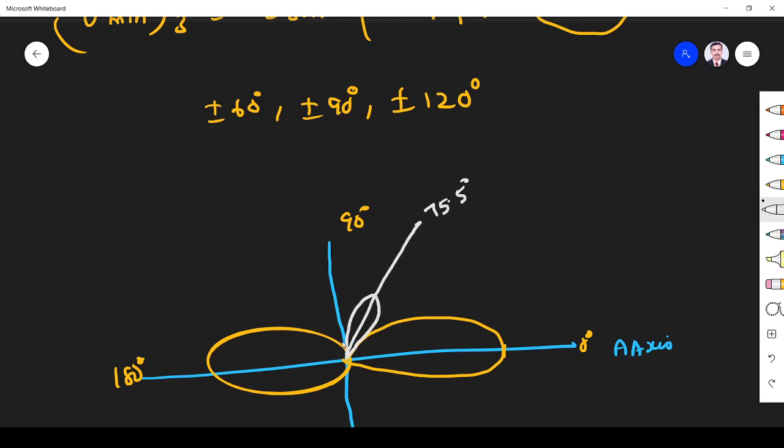And this is 104.5 degrees, where another minor lobe occurs. Similarly, we will have the mirrored ones at minus 75.5 and minus 104.5 here and here. So this is what the minor lobe maxima look like.